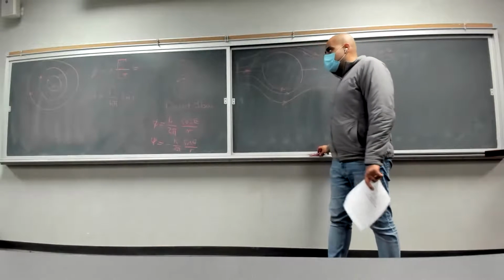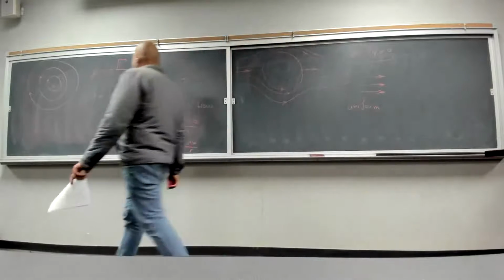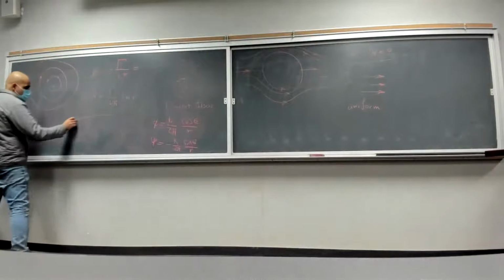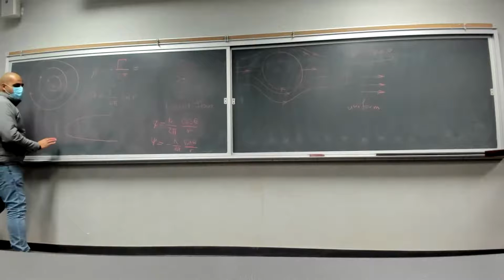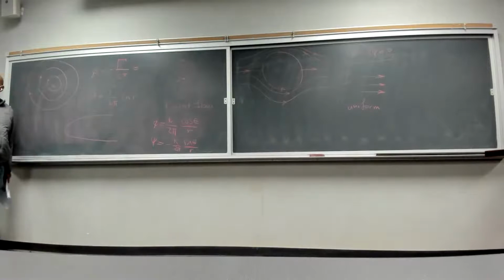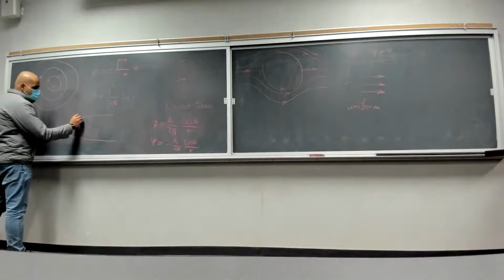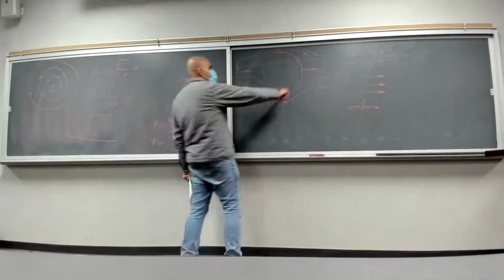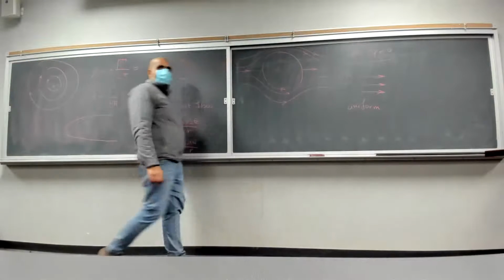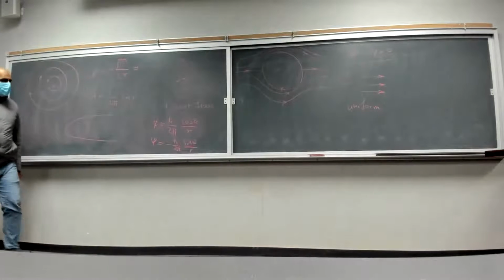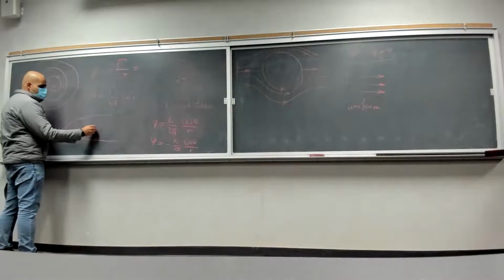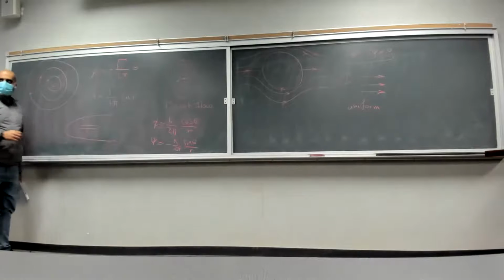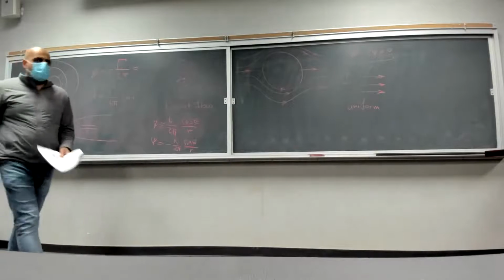Source flow gave us something that resembled an airfoil, right? Which was a semi-infinite body, right? Because you won't get the stagnation point at the end of your cylinder, right? Because at this part, your velocities are in the same direction. You're essentially adding to the velocity.